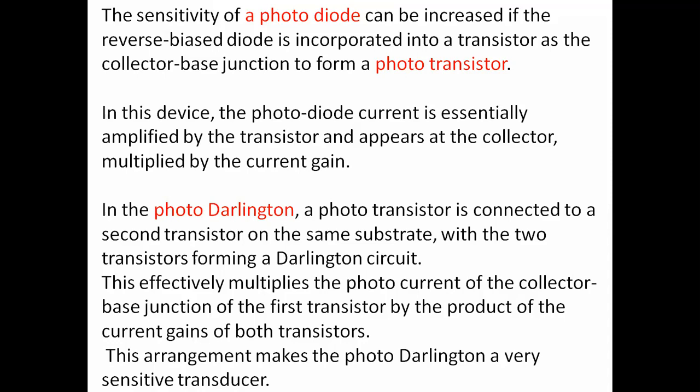At the base region of this phototransistor, the light falls on the base region. Depending upon that, charge carriers are generated at the junctions of the emitter, base and collector. So there is a formation of current between the points, and from that we can relate that current to the corresponding light intensity. Like this, we can use the phototransistor.